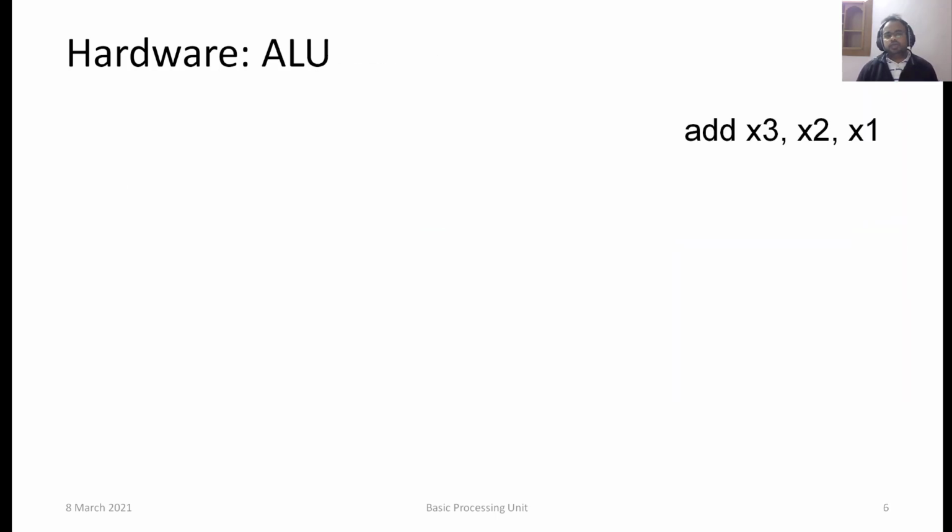Moving on, now let's look at the ALU itself, right? Like I mentioned in the previous lecture, you can imagine it as a collection of all the individual logic blocks, like the adder. It can be a ripple carry adder or carry look-ahead adder or anything like that, and Booth's multiplier, and circuits that will help us with division and shift operations, etc., and even the condition checks, right? Again, imagine that it's a black box and it will do the operation that it needs to perform.